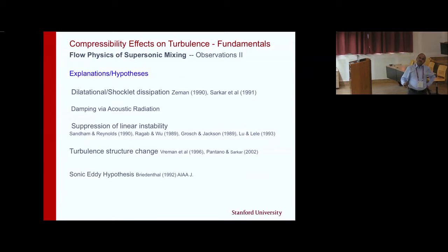In the early 90s, there was another hypothesis called the sonic eddy hypothesis from Bob Breidenthal from University of Washington. Bob came up with this very simple idea that turbulent eddies that are actively entraining cannot have a velocity difference across them that is more than the speed of sound. If the velocity difference across an eddy is more than the speed of sound, then they will not be able to communicate. Vortex induction, or Biot-Savart induction, which we use to think about the kinematic relationship between vorticity and velocity, is fine for incompressible or low speed flow. As you go compressible and high speed, one has to think about acoustic processes as well. And so this idea was put forward by Breidenthal.